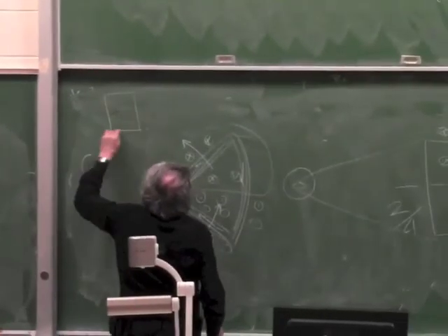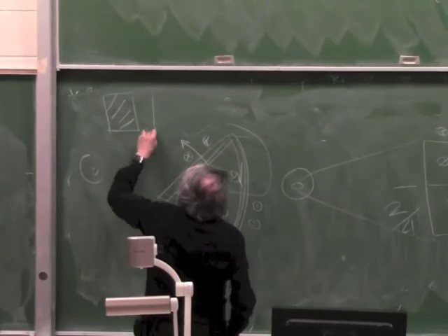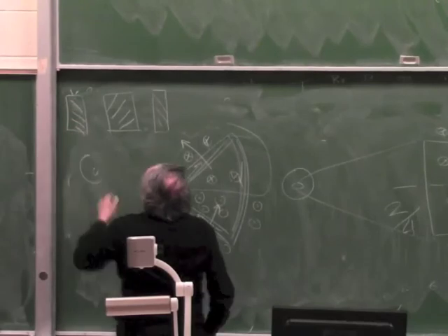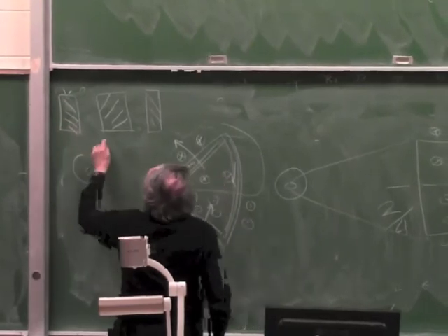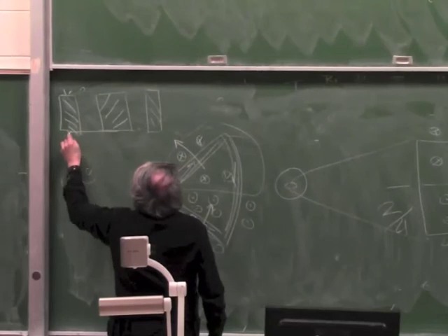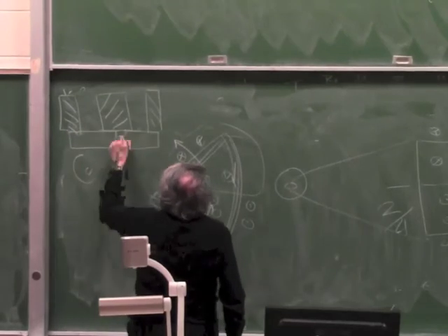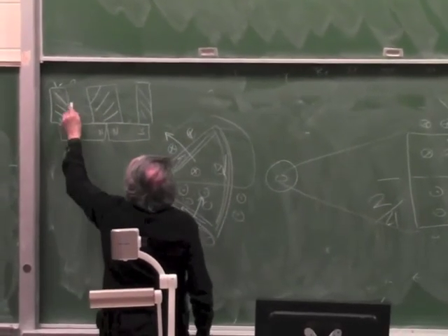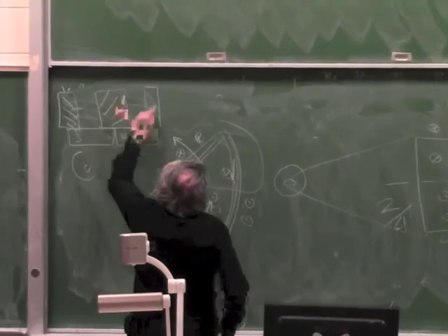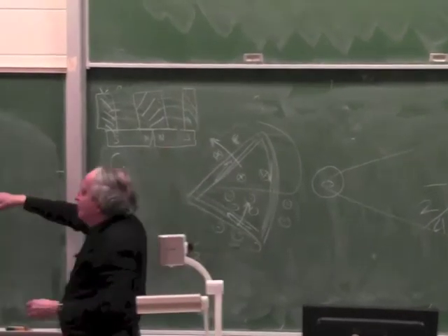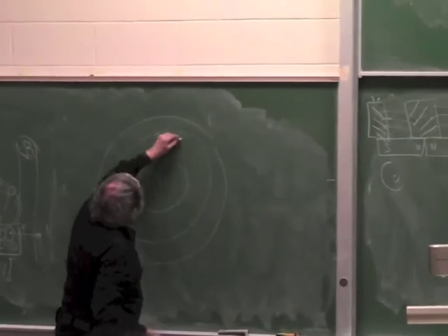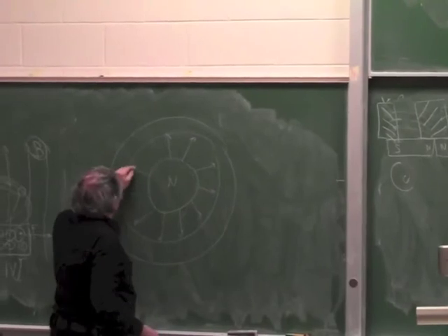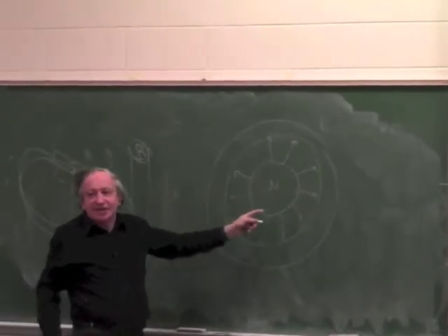Imagine if I have a piece of steel like this and I have a ring of steel which is like this. Okay, all I have to do is put a magnet here, or two magnets, which this is north, this is south, this is north, this is south. So now the field is going to close like this. So the field, looking from the top, will look like this. The field is trying to go from north to south. Again, all this is conventions, as I said. Okay, so does everybody understand how I made the radial field?